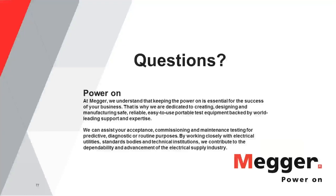Up until maybe the turn of the century or thereabouts, PIs were pretty generally used and pretty generally accepted, but now the readings of the insulation itself and the capabilities of the testers are going much higher. Now we have guys doing tests in the kilohm range, and they're doing a PI test, and they're getting very low PIs.